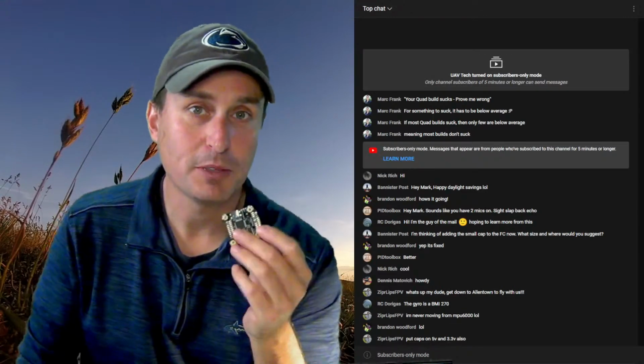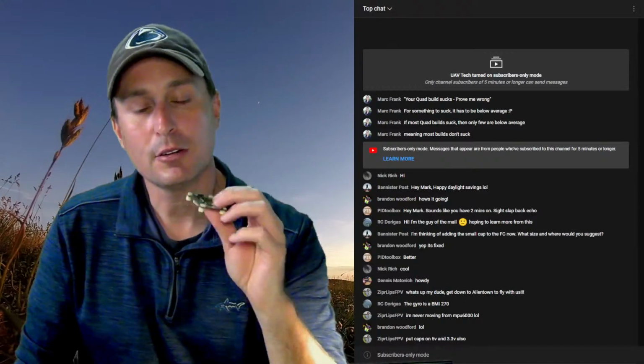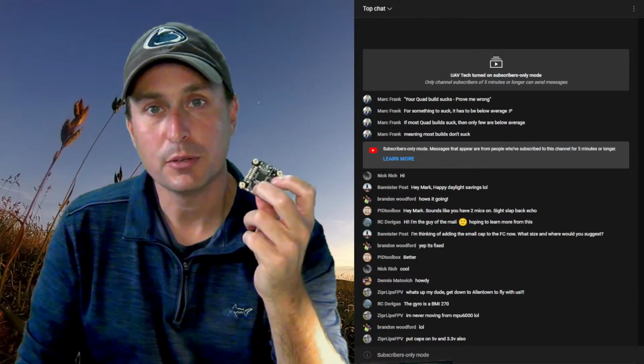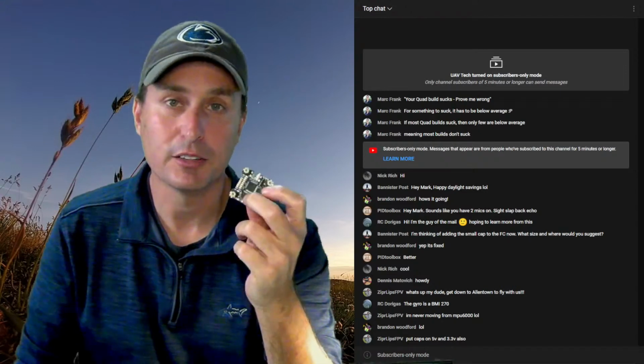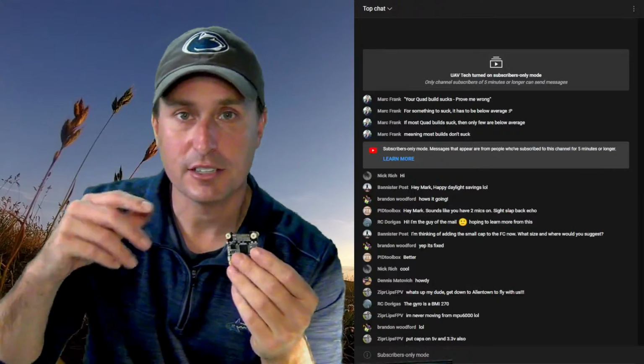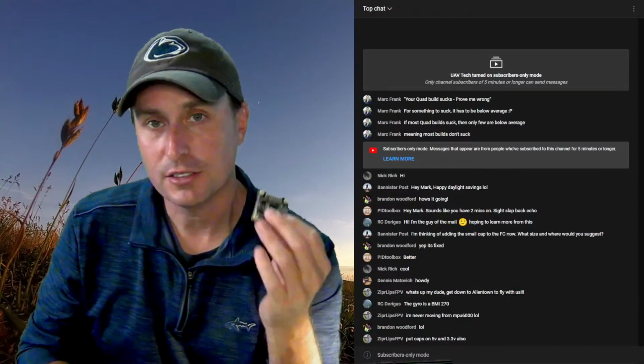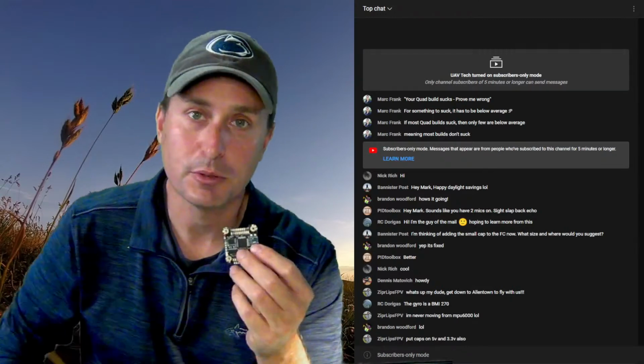The other option I haven't played with just yet is that your gyro is being powered on the 3.3 volt rail. VBAT comes in, and the regulators take it down to 5 volts and 3.3 volts. The processor and the gyro are powered on the 3.3.